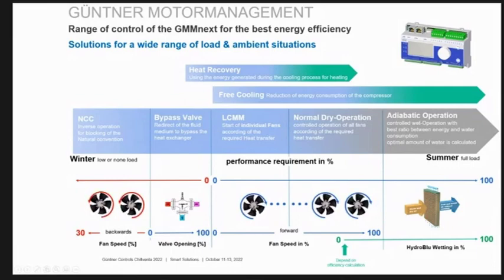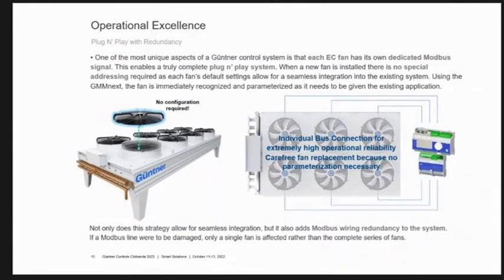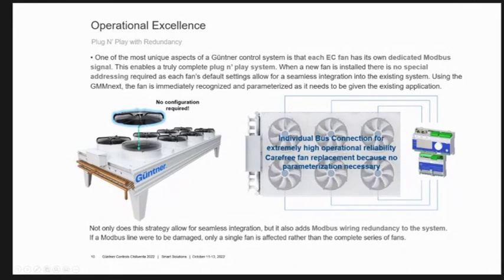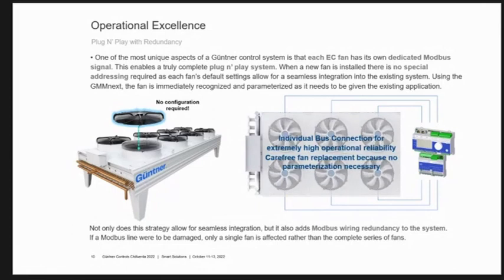So with our adiabatic side, and that's one thing I do want to talk about too, is the adiabatic control, but I'll get into that right now. Let's go over here. This slide shows how we have individual bus lines from each fan directly to the controller. So there's no configuration required. If you need to replace the fan, all you have to do is drop it in and rewire it, and it comes alive. I know a lot of technicians appreciate that, instead of having to program certain fans.